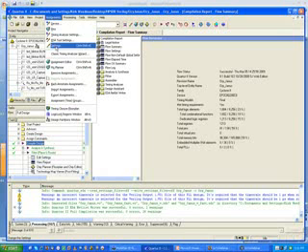One thing I could point out real quick is in the Quartus tools, remember I talked about when you synthesize stuff, I went through compile the design. You can click on this and tell it to start, or start again if you already compiled. The compiler has different options that you can feed it. In the assignment settings, let's look at some of these real quick. Here are some under analysis and synthesis settings. There are some optimization techniques, such as optimizing for speed or area or a balance in between.